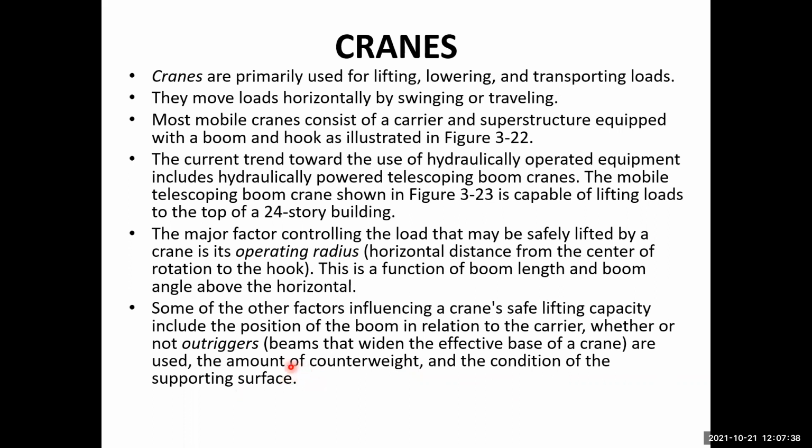So sometimes the beams are used, which effectively widen the base of the crane. So that means we want to provide more support to the crane, so that it can carry more loads. The counterweight at the base can also be increased to improve the capacity of the crane, and also the load carrying capacity depends on the condition of the surface on which the crane is placed.